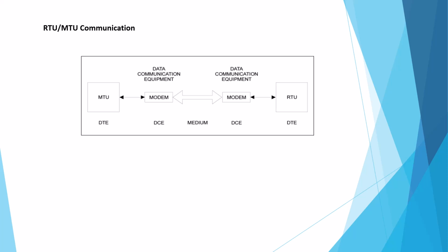For RTU and MTU communication, the MTU and RTU we always call data terminal equipment. The modem we call data communication equipment. So every MTU connection has a modem. Every RTU has a modem. Every modem has a radio. The radios just communicate with each other.